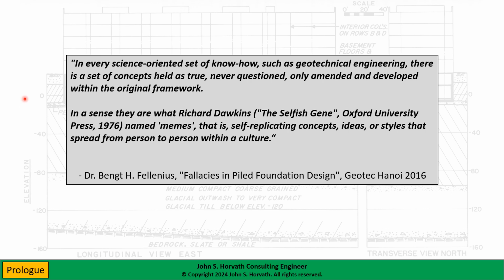In reality, it is soil stiffness and compressibility, settlement as defined by the geotechnical serviceability limit state, that is the way deep foundation elements should be designed for axial compressive loads. But that's a subject for another day. In my opinion, the issue of the coefficient of subgrade reaction and subgrade modeling is an even bigger meme in geotechnical and foundation engineering, simply because it's used for so many different things, in addition to mat or raft foundations.